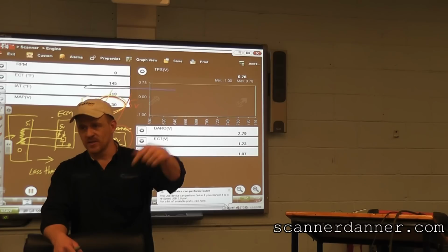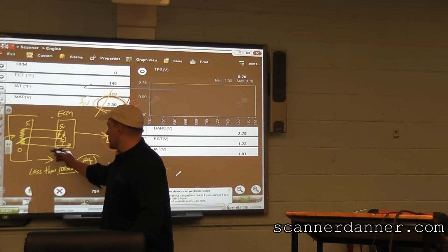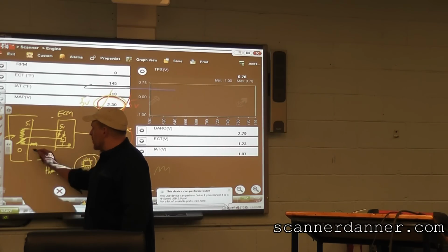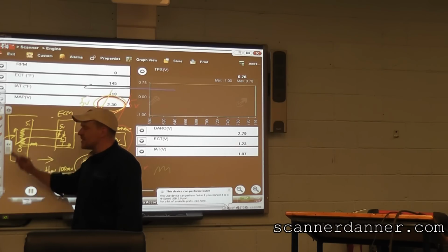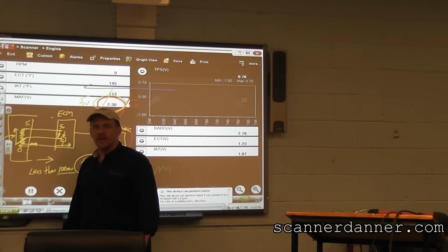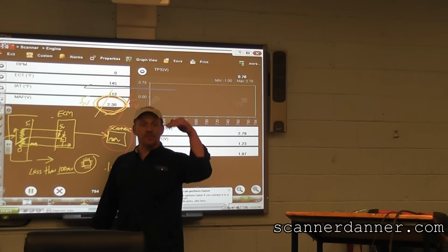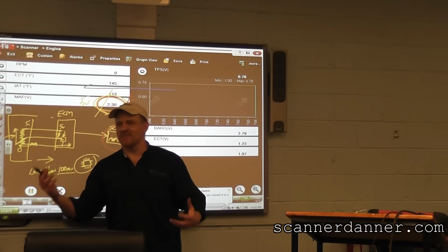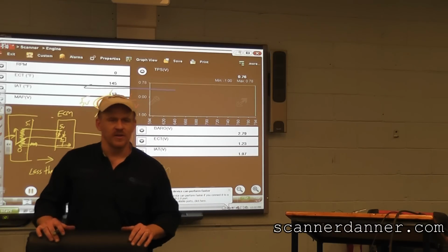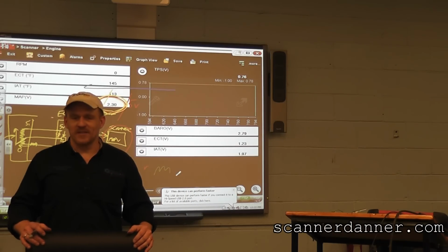One more check your ground voltage, make sure you're low on your ground. Because if you have resistance on your ground, won't that cause pressure to back up this way? And won't that cause my signal voltage to rise and be abnormal? And couldn't that cause this too? Yes and no. Yes, in that it would be elevated, but no, it would not be steady. We'd still have some function to it as it moved. It would just be out of range. Lots of thinking, but really, really easy to use.